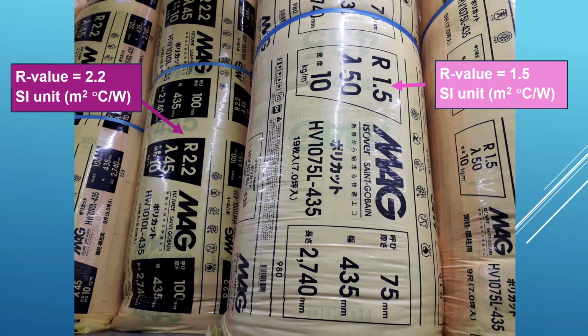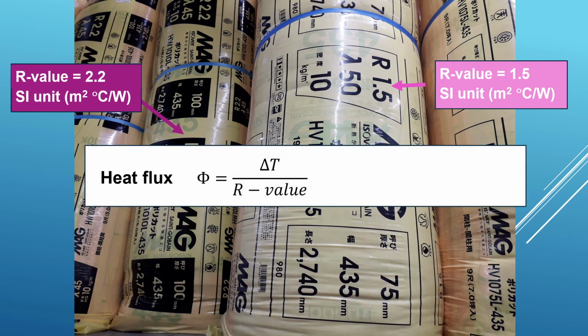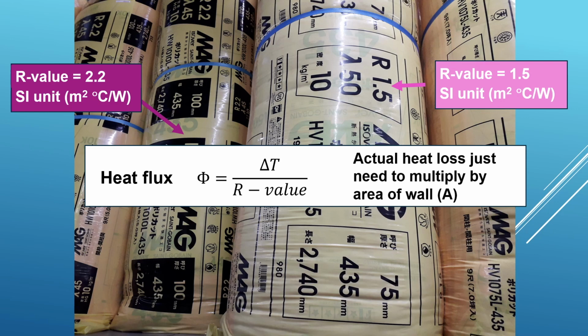Now we know how the amount of insulation is defined, we can easily calculate how much heat is conducted through a wall, for example. What we need to do is just take the temperature difference between inside and outside and divide it by the R value and multiply by the area of the wall.